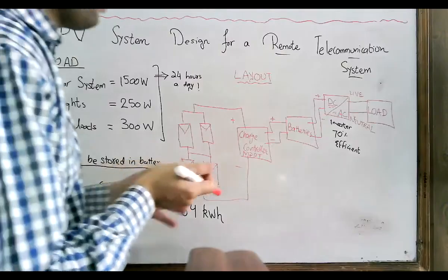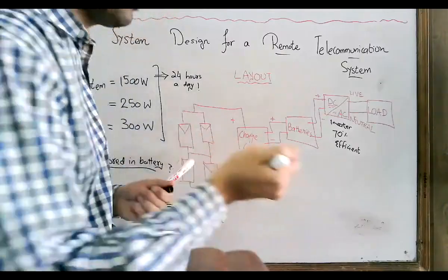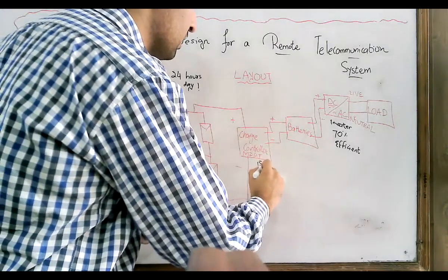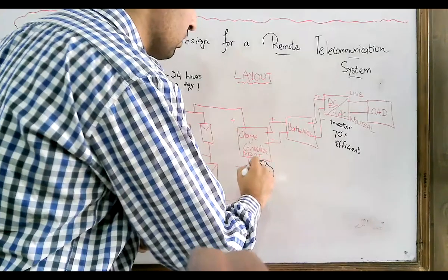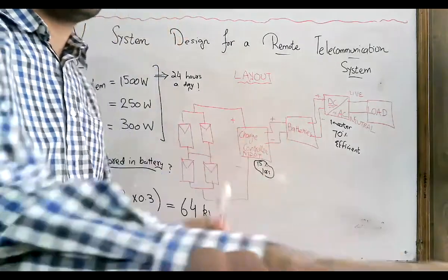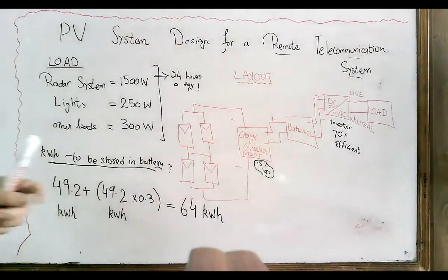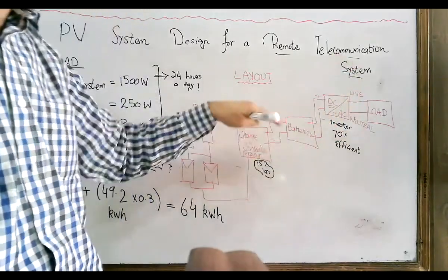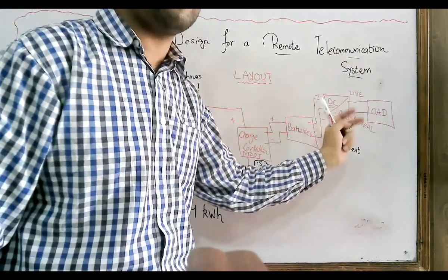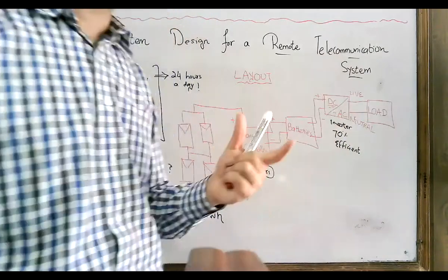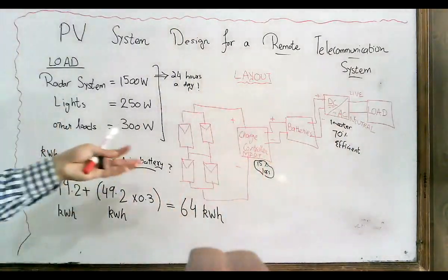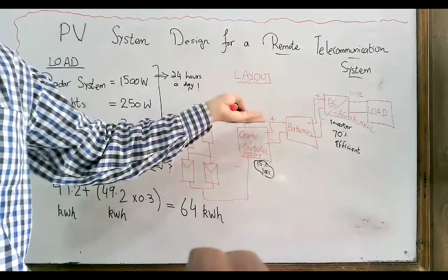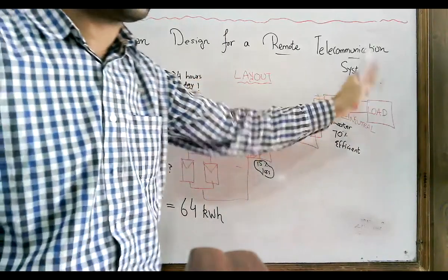One more thing, the battery charge controller is also inefficient. There is around 15% loss in it as well, but this loss varies according to the charging current. So as a thumb rule, whichever type of inverter it is, we just assume that our inverter is 70% efficient, because the 30% losses cover the inverter loss, as well as the losses in the charge controller and in your cables.